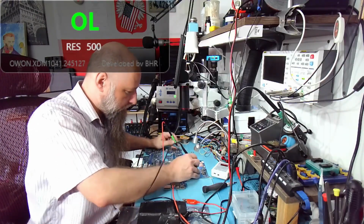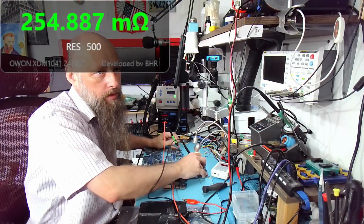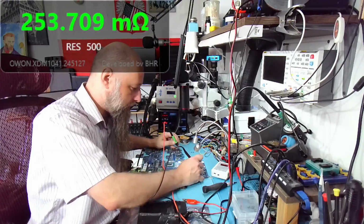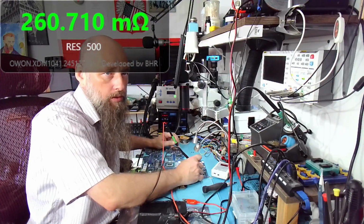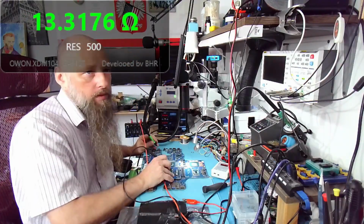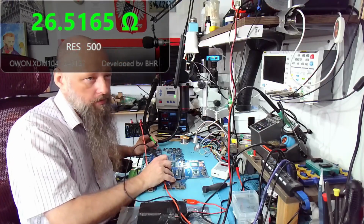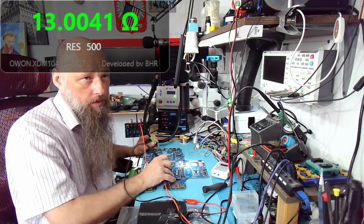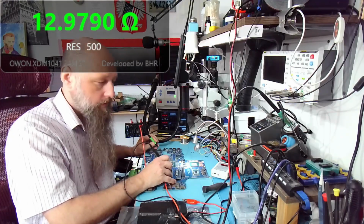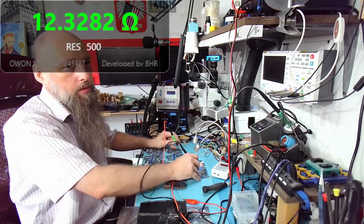And if we check on the original, on the same coil, we have 250 milliamps, right? So, yeah, this is no bueno. And these should be all the same, I think. And on the original, yeah, 13 ohms. That sounds about right. Anywhere from, I would say, maybe 4 or 5 ohms, 12, 13 ohms, yeah, this is good. So this is the resistance that the CPU should have, and we have 200 milliamps.